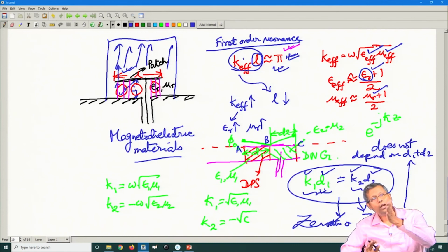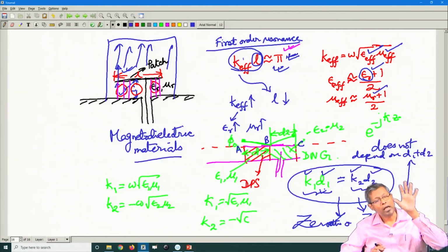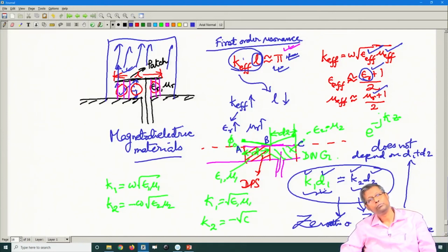It is not a difficult thing to miniaturize an antenna, but it is difficult to miniaturize an antenna and maintain an appreciably low quality factor. That is the difficult thing. To miniaturize a resonance, reduce the resonant frequency and maintain its efficiency is a much more difficult thing than sheer miniaturization, which by itself will carry little value if the efficiency is not adequate.